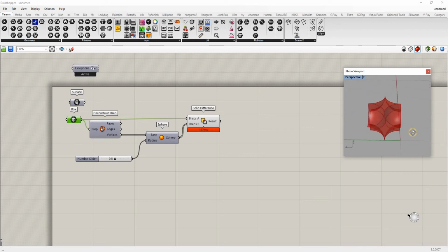Now I want to give it some variation so that when I put this on that surface, I can create some interesting patterns with it. If I tiled this together, it would make these sort of hemispheres across the surface. So the next thing I want to do is create another surface that I'm going to subtract from this.